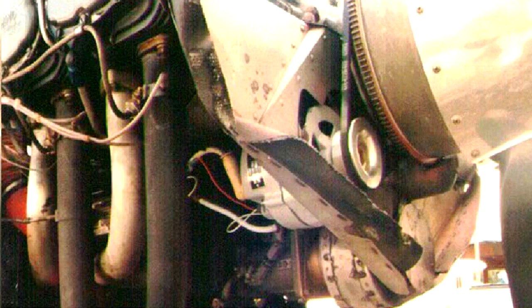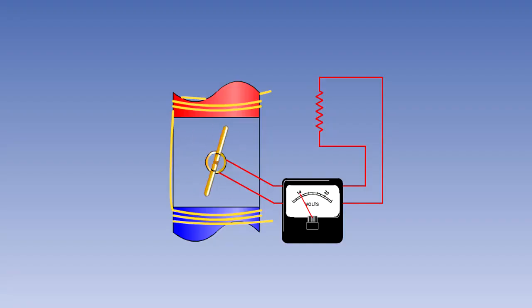The generator or alternator is driven by the engine using a drive belt or directly from the engine accessory gearbox, and therefore the speed of rotation of the armature or field is linked to the speed of rotation of the engine. Controlling the output voltage by controlling the speed of the engine is not normally a practical solution. In fact, it is necessary to maintain a constant voltage in spite of changes in engine speed.